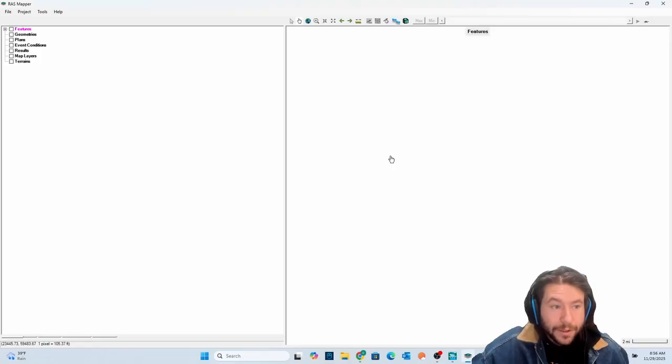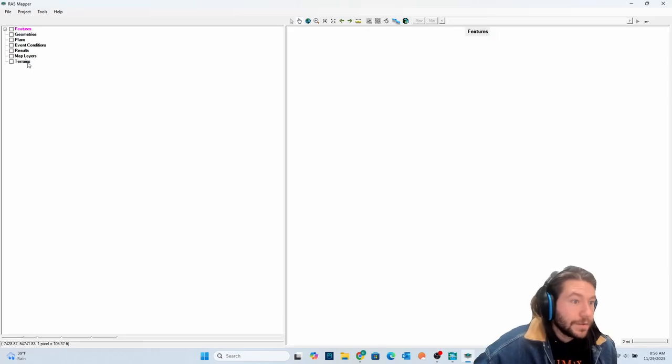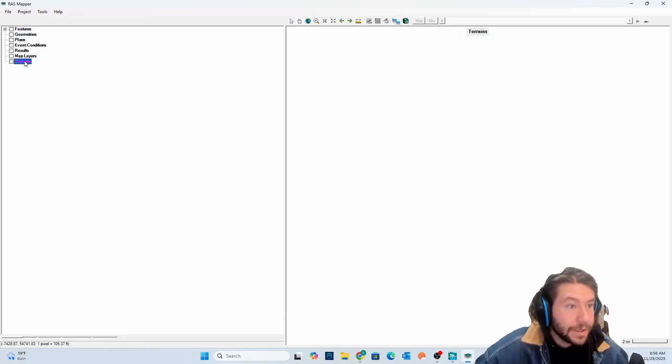And sometimes whenever you hit OK there, it does pop up with an error saying it's corrupted or something. Don't worry about that. Normally it's fine. It's just got an issue sometimes with the projection. It's missing like a title or something. So it doesn't quite load in 100% correct, but it'll do everything it's supposed to do here in HEC-RAS. So don't worry about that. I think it does do that for your project. So just hit OK and skip it, and it should load in just fine.